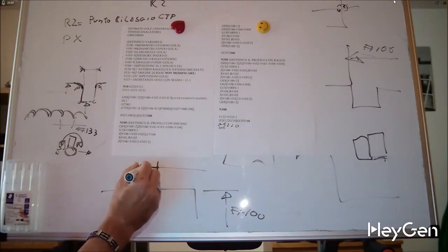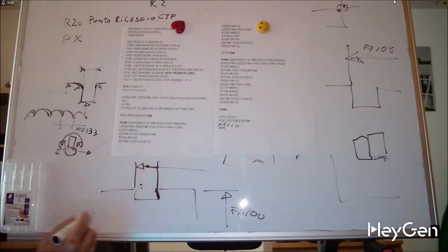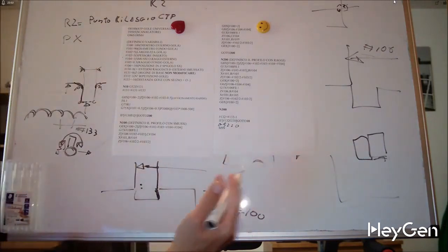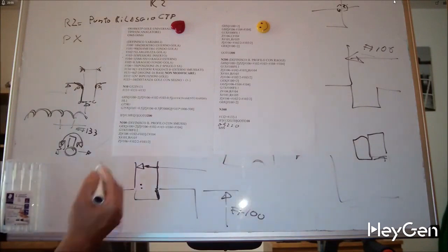Oh no, I brought it. Minus 0.5. What is this 0.5 for? It's for leaving a bit of excess material on this side. Here, I start making my groove, taking into account the side excess material and the thickness of the insert.